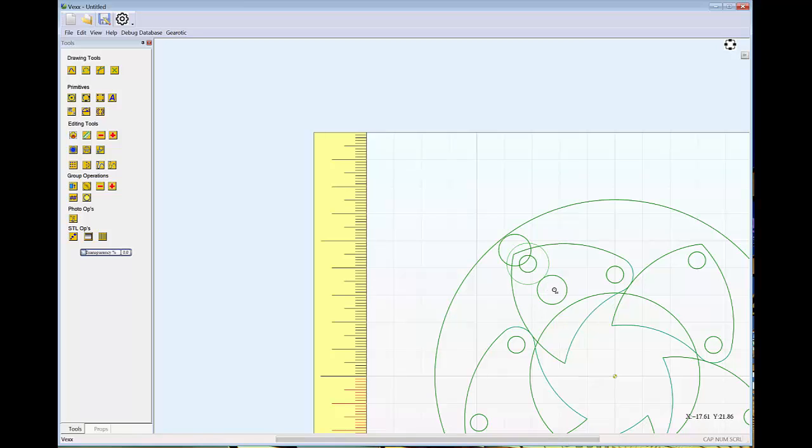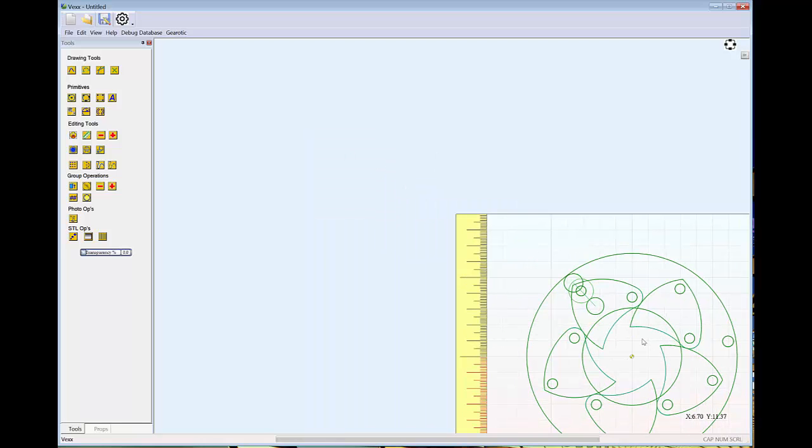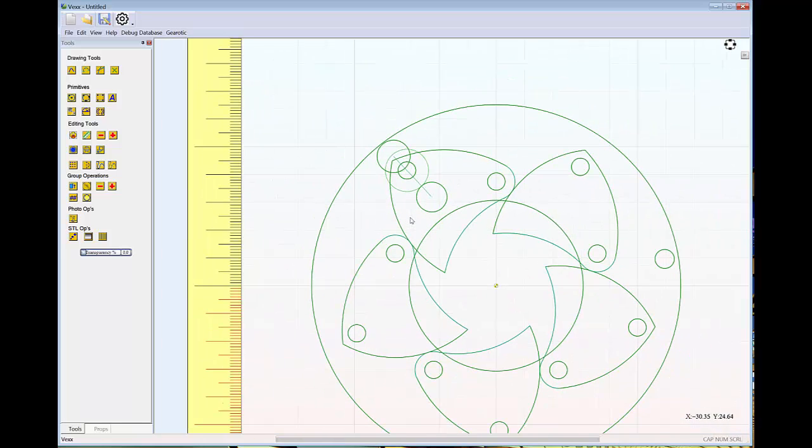The shape of this slot will really depend on how far you're going to run it in your control. So now I will choose a 3-point arc, and I will go from center circle of the outside to the center circle of the inside and conform the arc to the center of the middle one. And in this case, it's a straight line. We could have just drawn a line. So with that in mind, we can now take our line, or we can select that contour we just put on, and we'll hit delete and delete that.